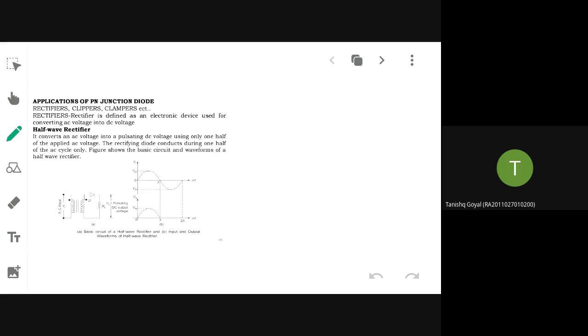You have conducted one laboratory experiment also. You have drawn the characteristics. In the reverse bias, how is the voltage present? It is constant. One straight line you are having. So it is preferably meant for what application? Voltage regulator. So what is a voltage regulator? The voltage remains constant regardless of whatever changes happen on the line side or the load side. The voltage will always be 5 volt means 5 volt, 6 volt means 6 volt. It will not change. That is the meaning of voltage regulator.